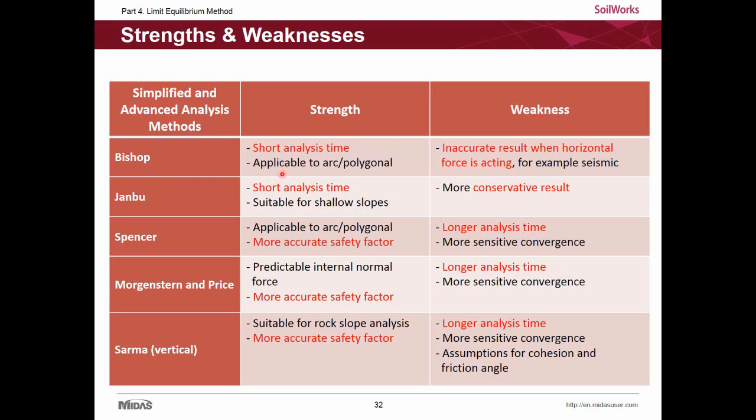For Janbu, the results are too conservative. With advanced analysis methods like Spencer's, MNP and Sarma, the analysis time is longer, but the factor of safety calculations are quite accurate, and these are well supported by MIDAS SoilWorks.